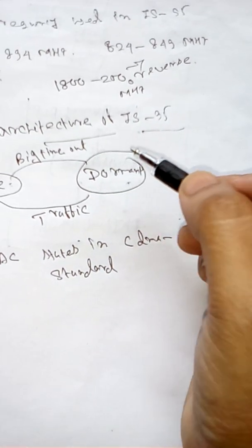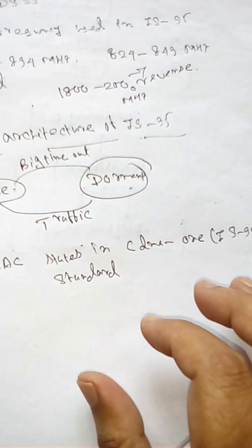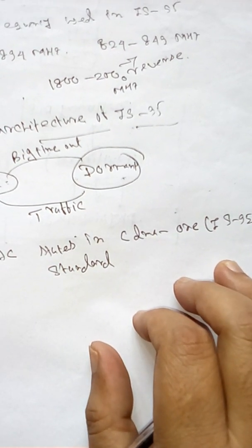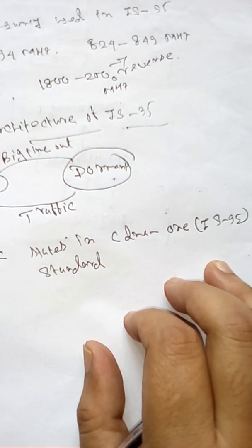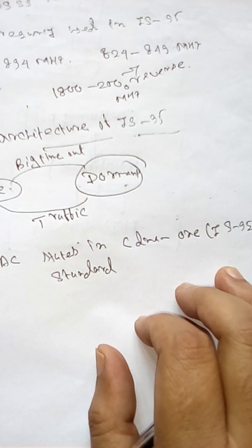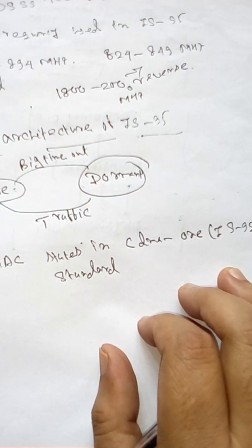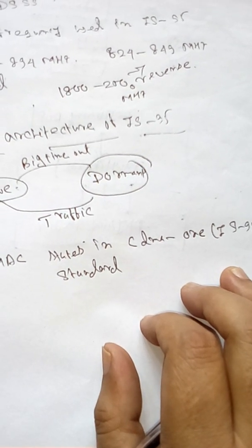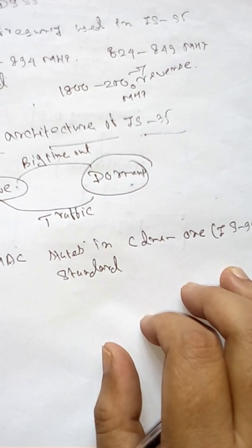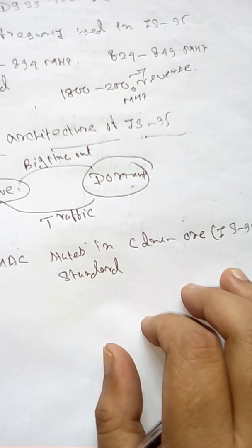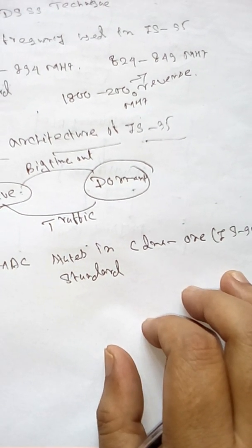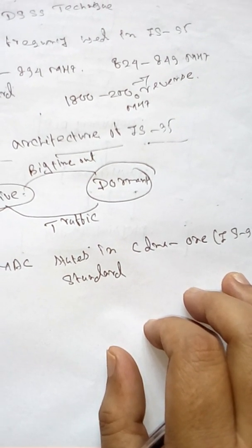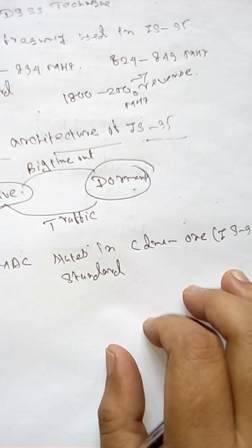So these are the important terms related to channels in IS-95. The forward channels are known as downlink channels, and they carry the traffic from the base station to the mobile station. Effectively it consists of 64 channels, and the respective logical channels are differentiated from one another by various CDMA spreading codes, called orthogonal codes or Walsh functions.